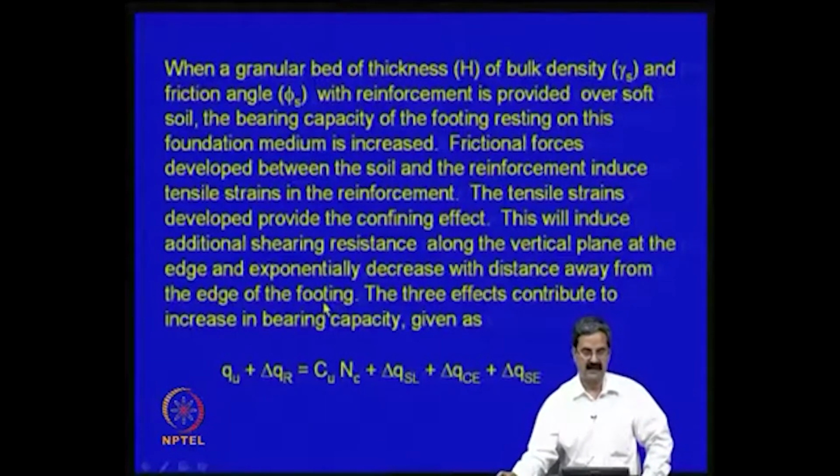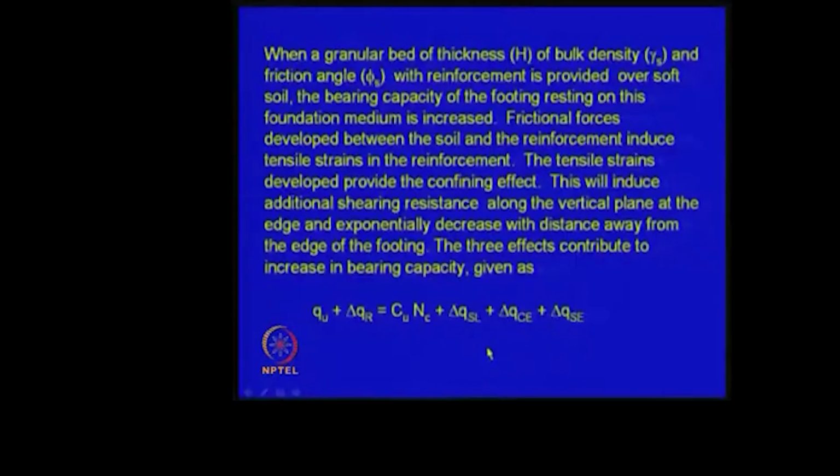So, one is the shear layer effect, the second is the confining effect, and the third one is the surcharge effect. All three of them contribute and increase the bearing capacity by these three terms. So, this is possible.